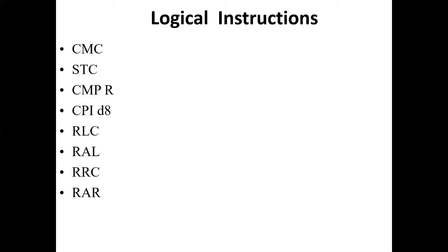This instruction is used to compare contents of the accumulator with R. The result of compare operation will be stored in the temporary register. Temporary register is an internal register that is not accessible to the programmer. As R can have any of the 8 values, there are 8 opcodes for this type of instruction. It occupies only 1 byte in memory.